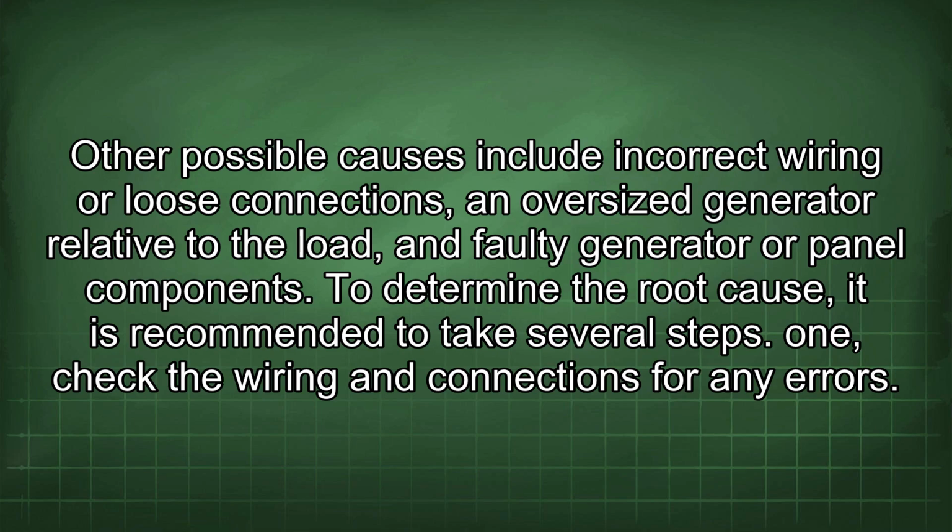Other possible causes include incorrect wiring or loose connections, an oversized generator relative to the load, and faulty generator or panel components. To determine the root cause, it is recommended to take several steps.